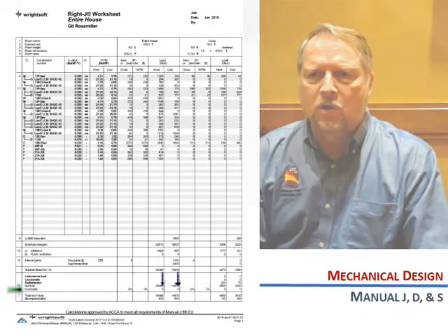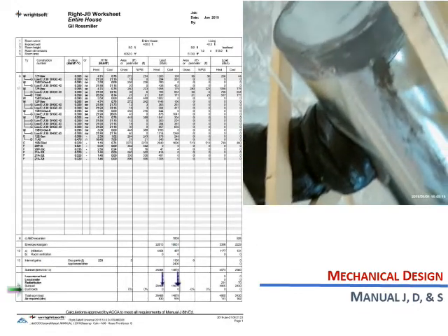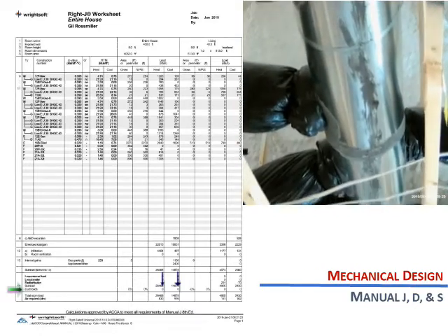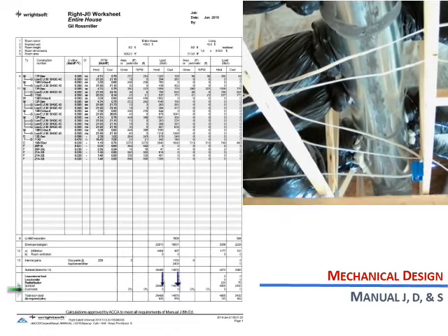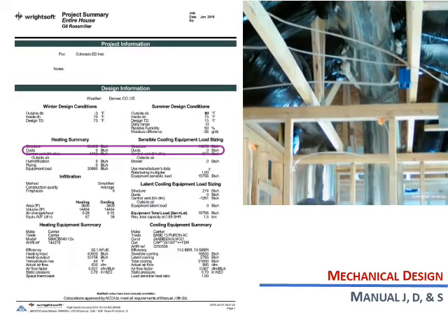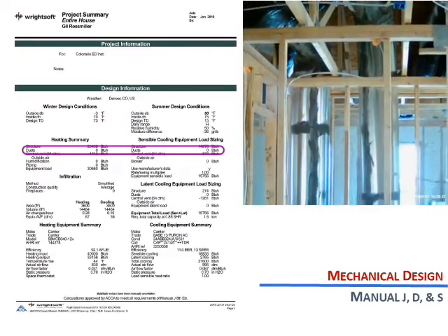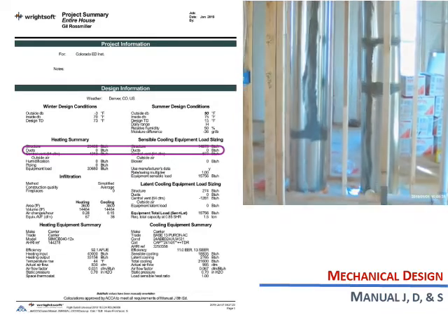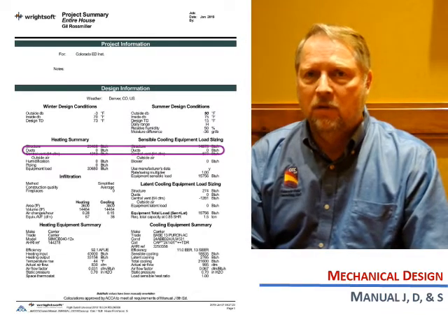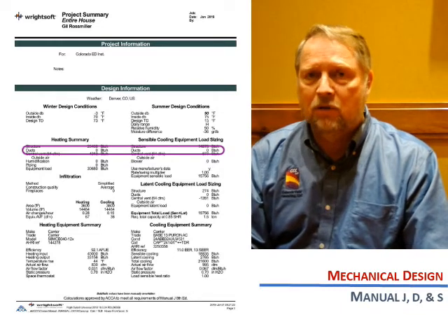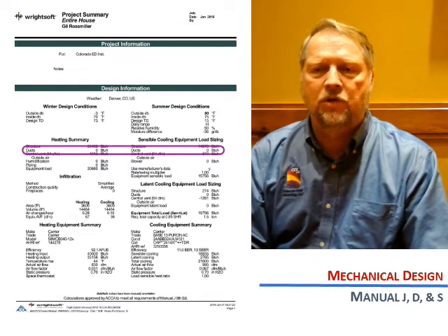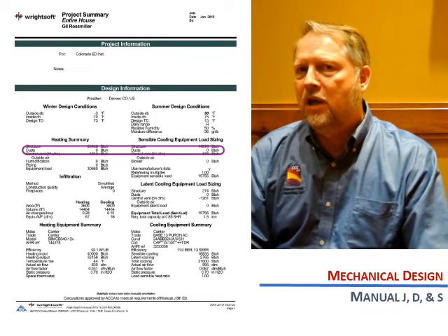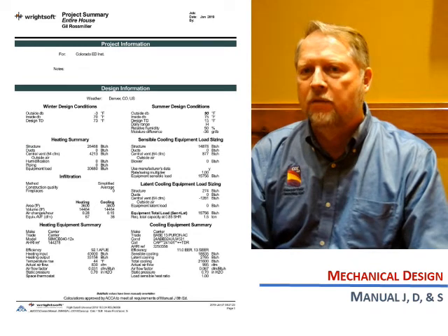The last thing we're looking at is ductwork load. Is the ductwork located inside or outside the thermal envelope? We need to know that. If we're showing a 0, there are no duct loads, which means all the ductwork is on the inside. Okay? If we see a load, they had better have ducts on the outside, ducts in the attic, for instance. If they're showing a load and the ducts are on the inside, they need to start over again.